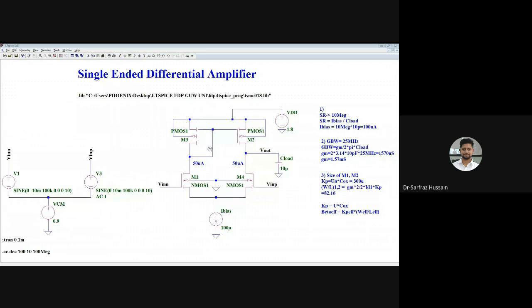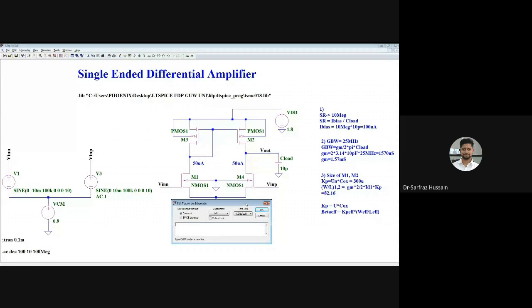So for PMOS transistors, what do we know? So this current flowing through here, we can calculate by putting up a formula. So let us calculate this as well. Actually the designing part may differ, for me it is different, for you it can be different. So the basic idea is to find out the W by L ratio for all these transistors.